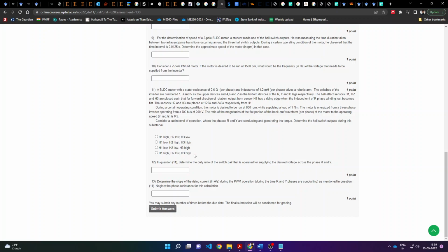Let's take I flowing through this. So voltage VA will be equal to I times R PH1 plus R PH2, phase 2, plus the potential drop across this, which will be L PH1 di by dt plus the other inductance term.